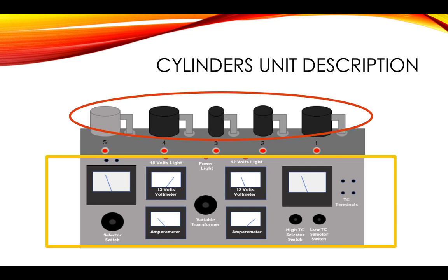The heat absorbed by the interior of the cylinder was transmitted into the exterior of the cylinder, which dissipated into the environment by radiation and convection. The heat transferred by convection depended on the shape and area of the surface, the velocity of the air currents, and the temperature difference between the surface of the cylinder and the environment.